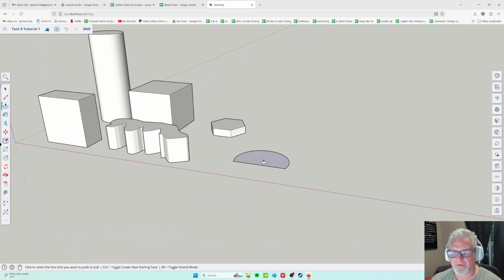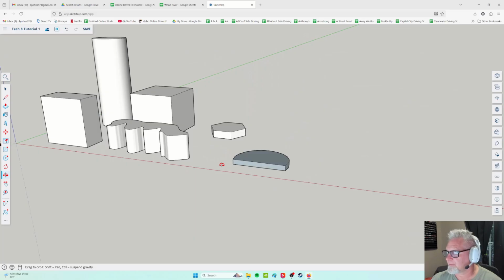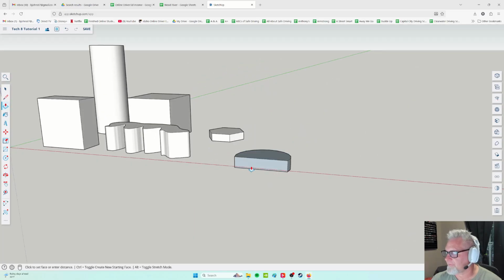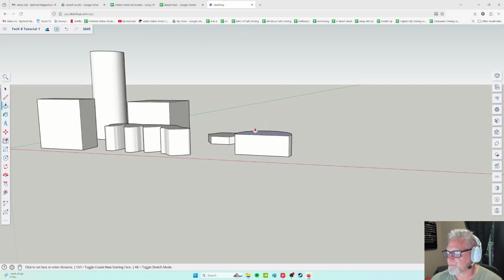And then this half arch thing. Let's make this the same height as Tie also. So this is about 6 feet. So, whoop, whoop, whoop, whoop. Oh, notice, hey, if I push down, see how it turned gray? That's not good. That means it's flipped inside out. So the inside color, gray, is on the outside of the shape. If I sent that to the 3D printer right now, it would fail. It would just be a mess of plastic spaghetti. So we're going to go, what did I say on this one? Oh, the height of Tie, like that. Okay.